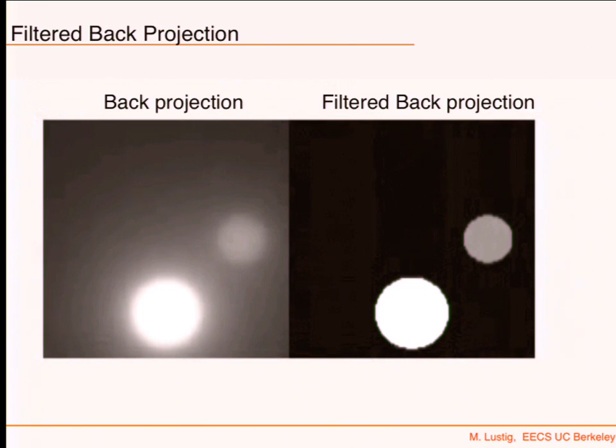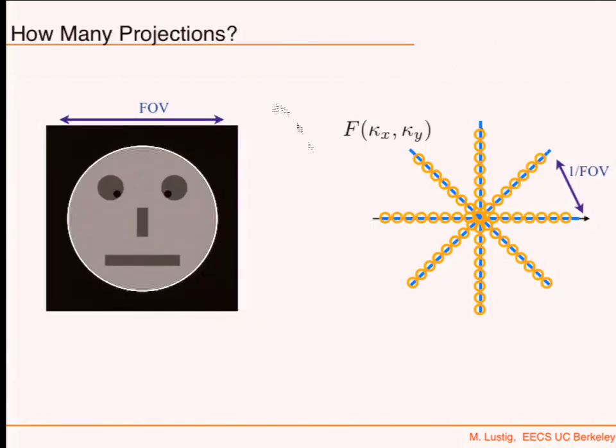And what is sampling in the frequency domain? Who cares if it's frequency domain or space domain? They're all interchangeable, right? If this, for example, was the spectrum and this was the image, I would have to sample at a certain rate such that I don't have aliasing of the frequencies. Now the case is that this is the image and this is the spectrum, and I effectively make measurements here. So I need a certain rate such that I don't have aliasing.